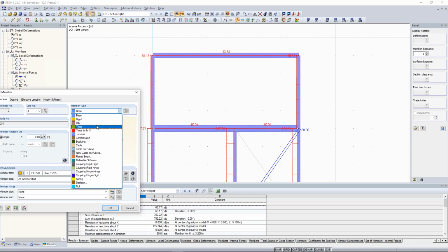When you have trusses, for example, a truss is a beam, and at that beam you have hinges at both ends. So at the end of this truss, you wouldn't have any bending moments. Yeah. And the same with tension and compression member types and so on. You have a big choice of these member types. But the most important are the beam, truss, and also this tension and compression. Okay, good. Later we come back also to the ribs, but this is another story.